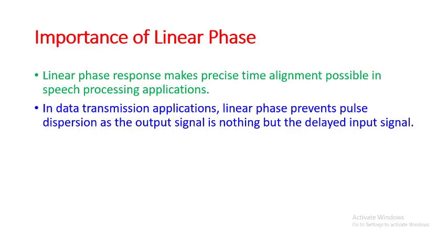Then another important thing is that FIR filters can be designed with exact linear phase. Now what is the importance, what is the application? The application is great in speech processing and its extended versions such as audio processing, video processing, augmented reality, virtual reality. That is a huge application of an FIR filter, because the linear phase response meets the precise time alignment requirement of these kinds of applications.